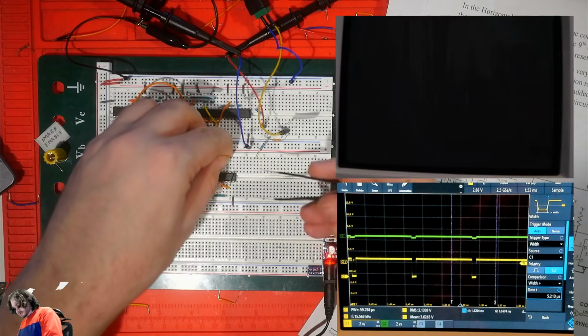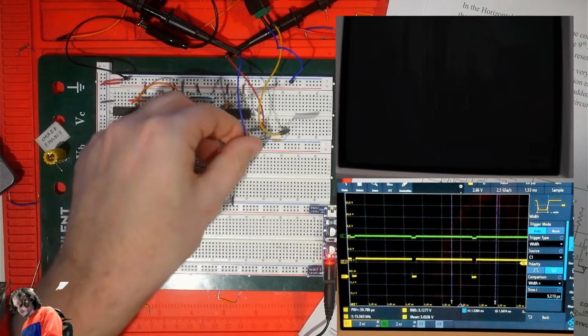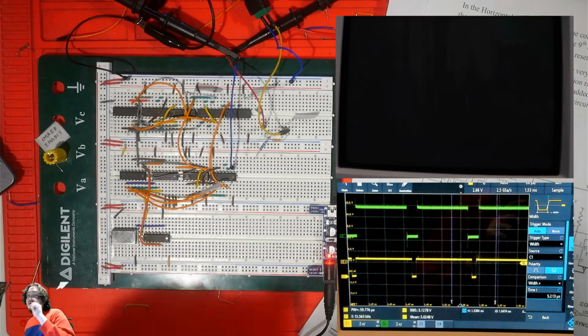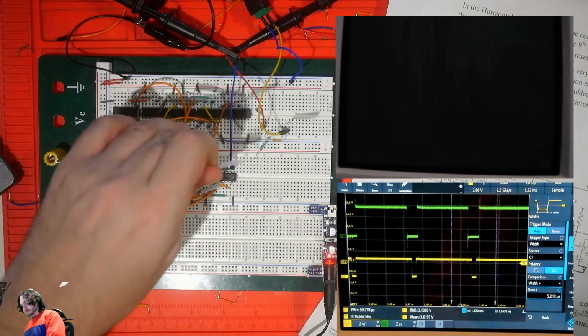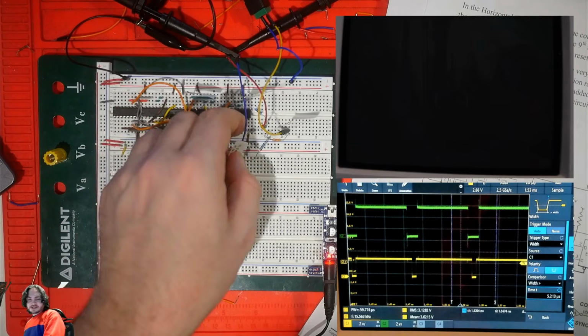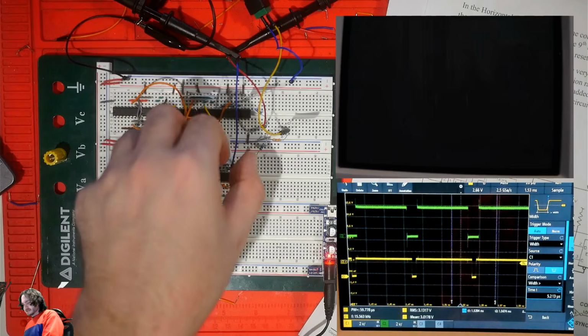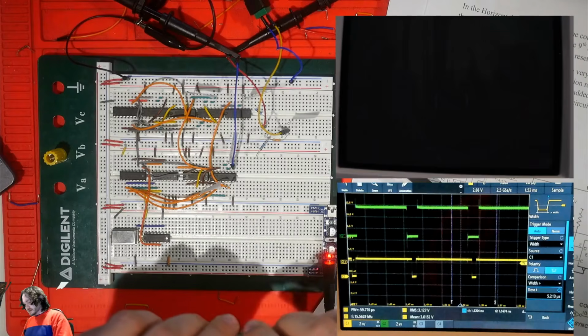And then connect those two NAND gate inputs to each other, the output becomes a signal that is positive, that is high when we want to be sending image data. And this is image enable. The utility of this is that we can now gate, for instance, with an AND gate, any pattern or image data that we are sending.